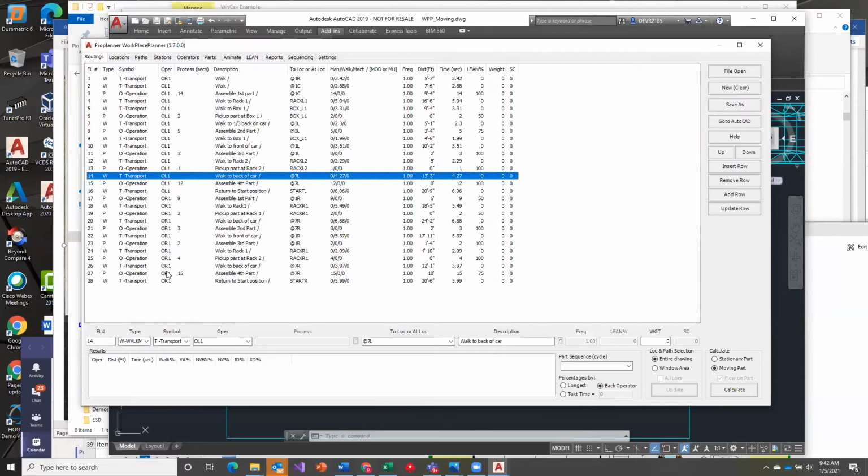done here. It would only be if I have a synchronization event, where I'm specifically requiring, let's say, a dashboard installation or a headliner installation, where operator 1 and 2, right and left, have to both be available at the same time, that I would list all the tasks before that headliner event for left and right, then have my synchronization event, then list all the tasks that are being done after that event.